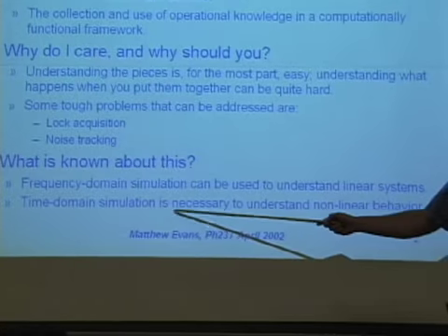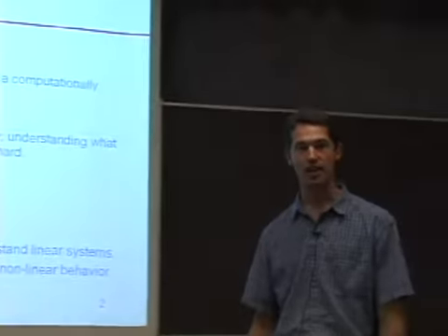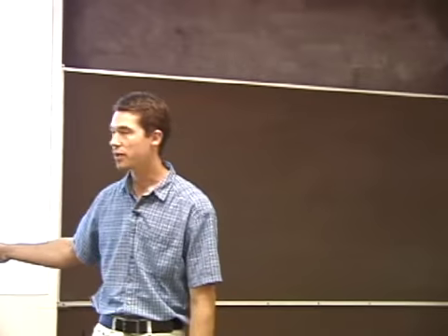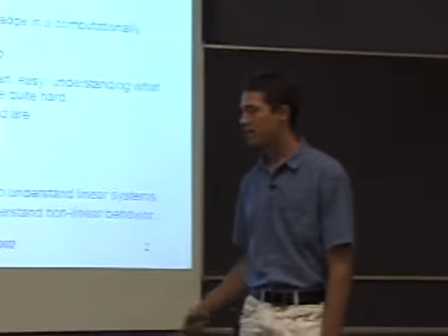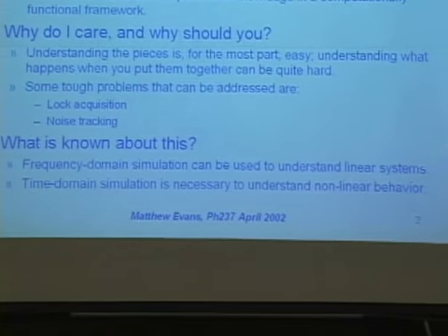The second part here, time domain simulations, is what you need when you want to understand systems which are nonlinear. They have some nonlinear behavior, and then all of the frequency domain analysis falls apart. To understand these things, you pretty much have to do them in the time domain, and the nonlinear response, whatever it is, is something that you describe in the time domain.